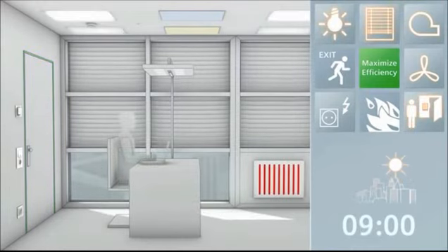At the start of work at 9 a.m., the functions are automatically activated, depending on whether anyone is in the room. The presence of people is detected by the access controller. The room temperature controller ensures an optimal indoor climate through proper heating and ventilation. Lighting is switched on by presence detectors or manually. The sun protection collector opens the window blinds and allows daylight into the room. At the same time, it prevents dazzling or heating by direct sunlight.